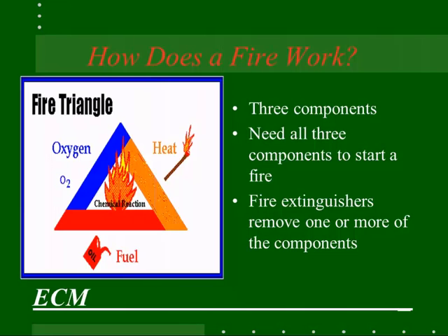I was in a dealership and body shop last week that for whatever reason had all carbon dioxide extinguishers, that's going to replace the oxygen and make the fire go out. And then if you're the more typical dealership and also in your offices, you're probably going to have a combination dry chemical extinguisher, and you're spraying that over the bottom of the fire to cover the source of the fuel. And that's how you're taking out the bottom of the triangle with those.